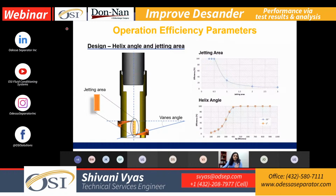So that's what it's saying: your jetting area is what's going to make that difference, and this is your vane angles on every helix that's inside your Desander. So your jetting area is going to be one of the ones that creates the most difference in how you're differentiating the particle. The smaller the jetting area, the more efficiency you're going to have, versus the simulation on helix angle that we had, where you have your 1 degree versus 10 degree. You can see it does not make much of a difference. It's almost the same on this one.